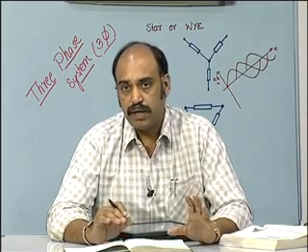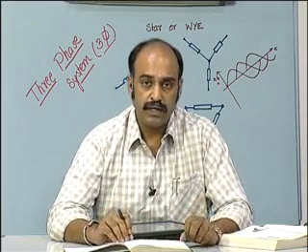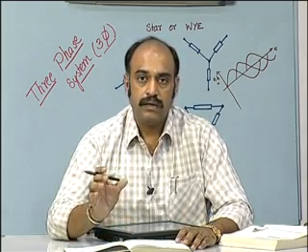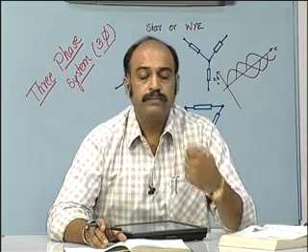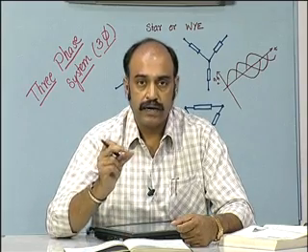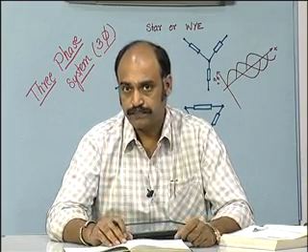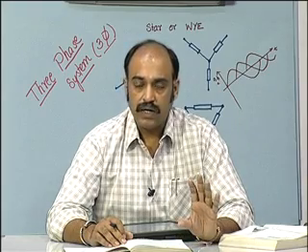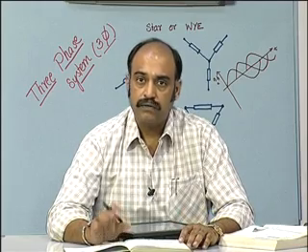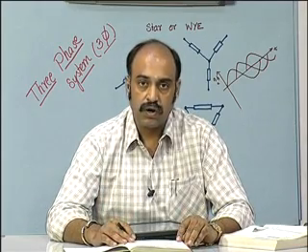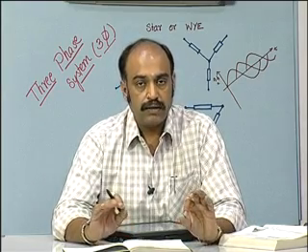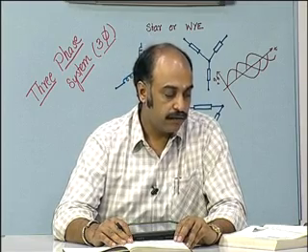The other method is by using watt meters. One may use 2 watt meters in the case of a 3-phase 3-wire system, that is, where neutral is not available. So, 1 watt meter may be connected to one of the lines, and the other watt meter can be connected to the other line, with the potential coils having the same third line as the reference. Then the values of the 2 watt meters are summed up to get the effective total power that is drawn from the source, or the total VA that is drawn from the source.